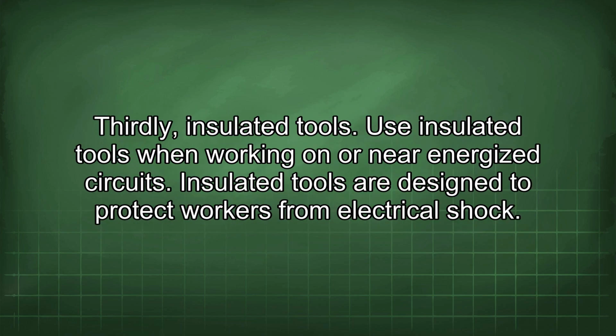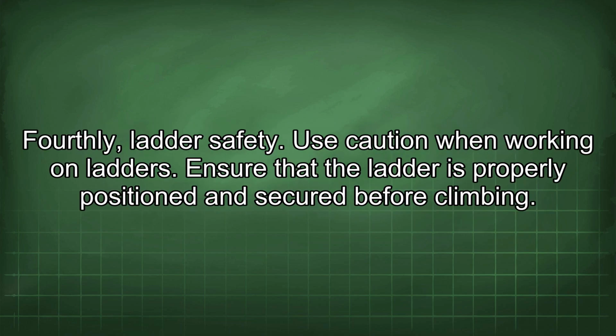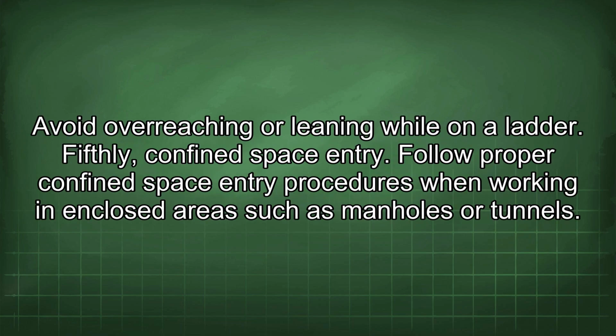Thirdly, insulated tools. Use insulated tools when working on or near energized circuits. Insulated tools are designed to protect workers from electrical shock. Fourthly, ladder safety. Use caution when working on ladders. Ensure that the ladder is properly positioned and secured before climbing. Avoid overreaching or leaning while on a ladder.